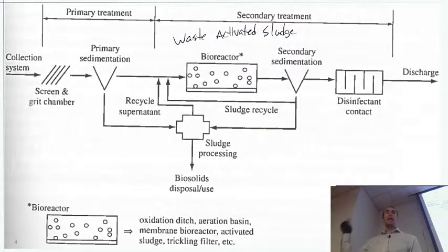Sometimes we will also do anaerobic, and perhaps if we have both, we might consider both of those together, the secondary treatment steps. But the basic thing would be aeration. And if we're discharging to a surface, we always want to have aeration at least once in the system to make sure we're discharging water that is not going to demand a bunch of oxygen. We'll talk about oxygen demand quite a bit.